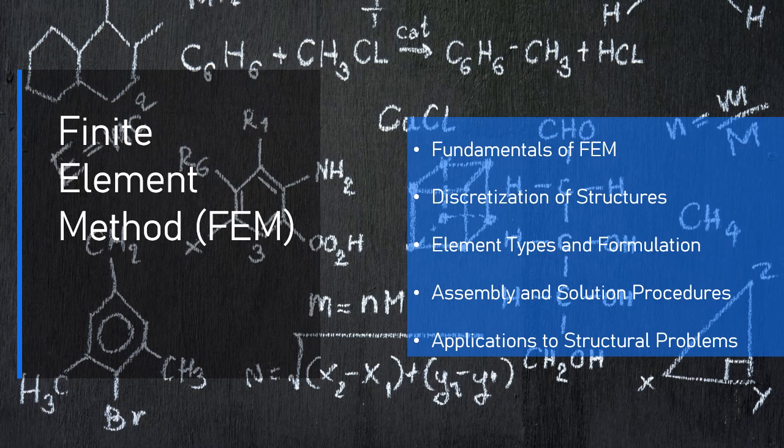4.6. Meshing considerations. When discretizing a structure, certain considerations should be kept in mind to ensure an accurate and efficient analysis. Element quality. Elements should be as close to regular shapes, e.g., squares, cubes, as possible. Irregular shapes can lead to inaccurate results. Element size. Smaller elements, finer mesh, capture the behavior of the structure more accurately, especially in regions with high gradients of stress or strain.